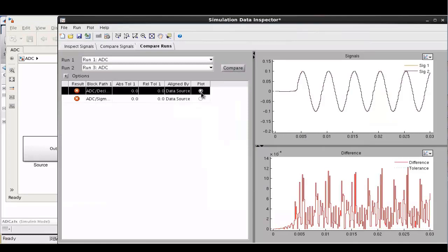Now you can see that actually the differences are much more relevant. You need to make sure that a fixed step solver is used. This is essentially the most critical step in the entire translation. Essentially, it is the task of the user to assess when good is good enough and find the most suitable trade-off between simulation speed and accurate result.